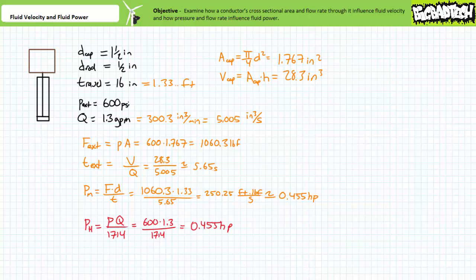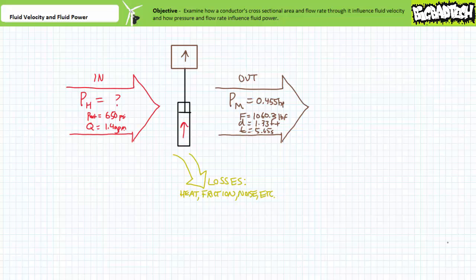Using the shortcut, one does not need to know actuator dimensions, functional area, volume, Pascal's law, nor actuation time. One simply looks at observed pressure and flow rate and walks away with a fluid power figure. Now realize this simple example is assuming there is 100% efficiency, an obvious fallacy.